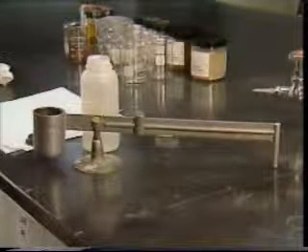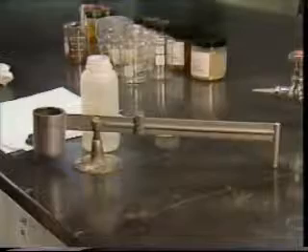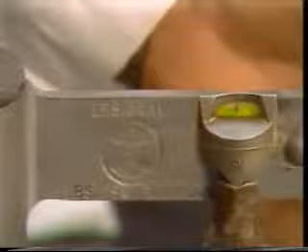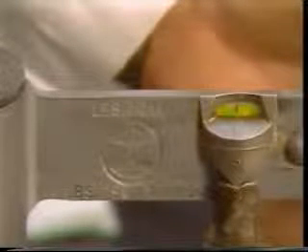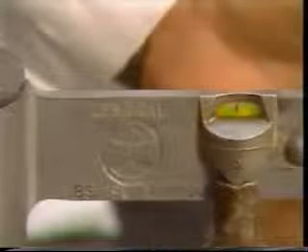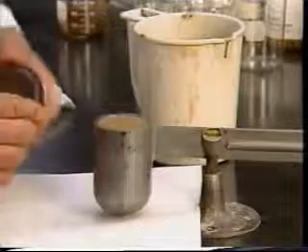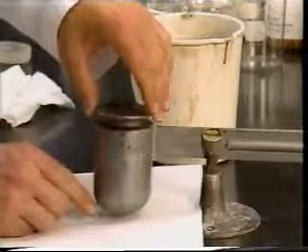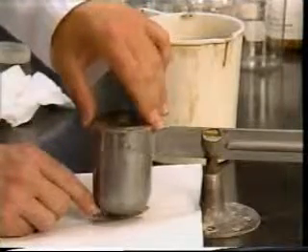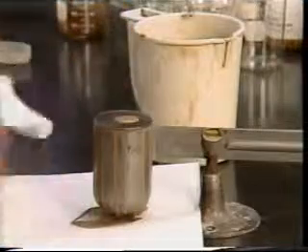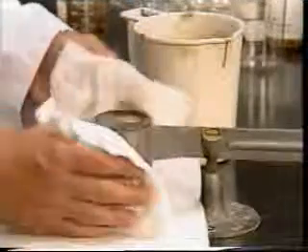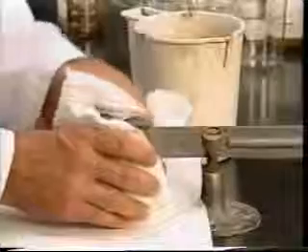This balance consists of a base and graduated arm with cup, lid, knife edge, spirit level, and counterweight. The scales on the arm may include psi per 1,000 feet, pounds per gallon, pounds per cubic foot, or specific gravity. After collecting a sample of mud from the pit, the mud cup is filled to overflow. The lid is placed on the cup and rotated to seat firmly. Some mud will squeeze out of the vent hole in the lid center.